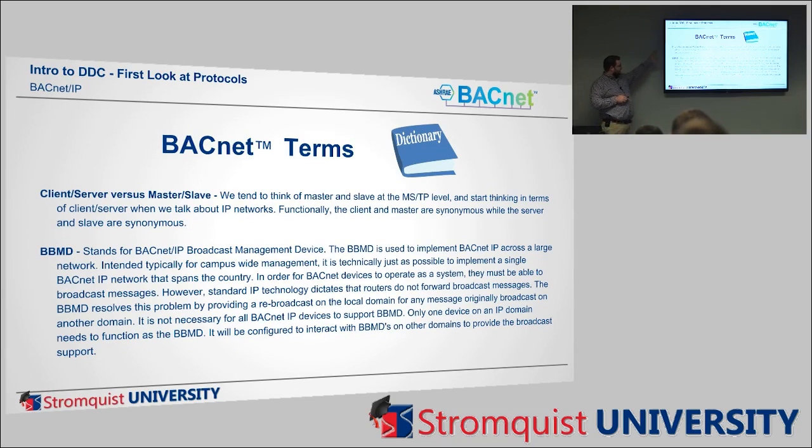This is more advanced. I just wanted to put this on the slide so when you do get the slide, you've got a reference to them. This is a pretty good explanation of client-server versus master-slave, that terminology. Client-server is more terminology used when you're talking about BACnet IP. Master-slave is when you're talking about MSTP, the 2-wire bus.